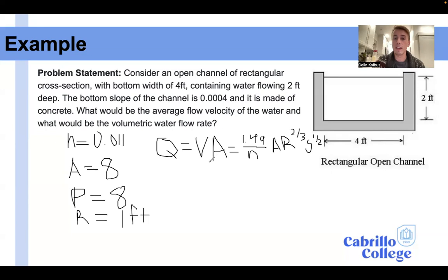And you'll notice if I cross out area here in both these equations, I really am just working with the stream's velocity. Flow rate equals velocity times area. And so the Manning's equation is really just dealing with the velocity of the river ultimately. That's what's being impacted by our roughness coefficient, by our hydraulic radius, and our slope.